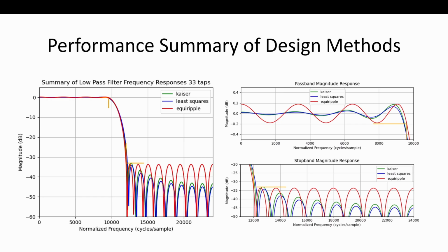It just comes so close to the optimum least squares, right, in terms of its performance, as far as a good window filter to use. Least squares is optimum in the least squared sense. You can't get better when you talk about your least error from a target sample by sample, right? So it's the best you can do. And the Kaiser window is coming pretty close to that. And you know, to the extent you care about that difference, it's good enough, right, in terms of that.